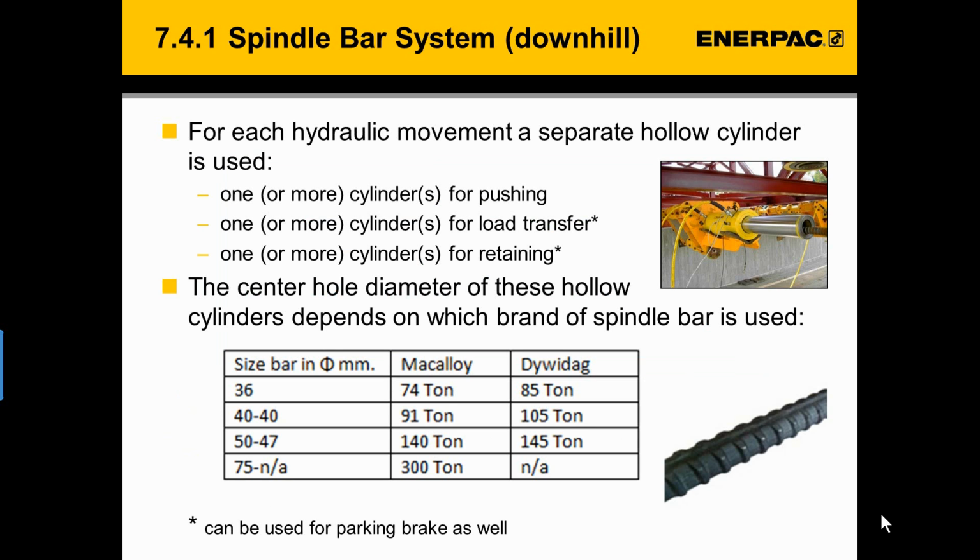Looking more closely at the movements which are necessary, you need to count with one or more hollow cylinders dedicated for pushing, one or more hollow cylinders dedicated for load transfer, and one or more hollow cylinders dedicated for retaining. The cylinders for load transfer and retaining can also be used as parking brake.